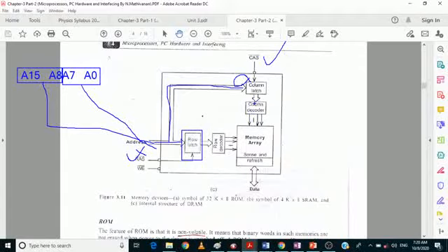Now, as we have the row address as well as the column address, depending on the control signal, write enable signal or whatever it is, the microprocessor gives the instructions by using one of the control signals. Depending on the control signal, the DRAM is going to perform the memory write operation or the memory read operation, or it is going to perform the memory refreshing operation also. So refreshing is going to be done with the help of the row and column format.